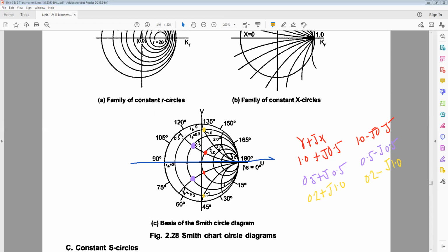Like that, you can assume where the point we got is P. P means from the origin we plot a point P as the normalized impedance, that is ZR by Z0, nothing but Zn, the normalized impedance, and extend this point up to the point M. You take the distances OP by OM or OQ.